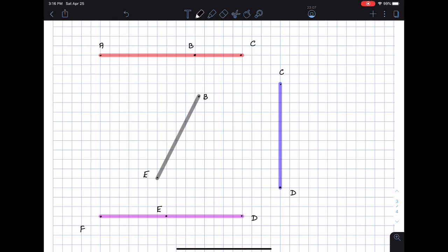So let's start off by drawing all these forces, and we see that at the pins B, C, D, and E, the forces acting are equal and opposite. Look at the bar BE, this is a two-force member, right? The bar BE does not have any other forces acting on it except at points B and E, so this is a two-force member or a two-force bar.